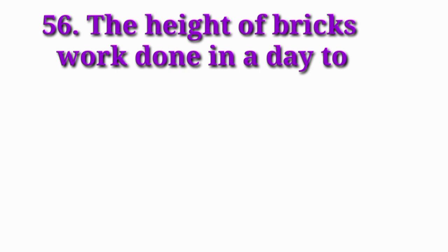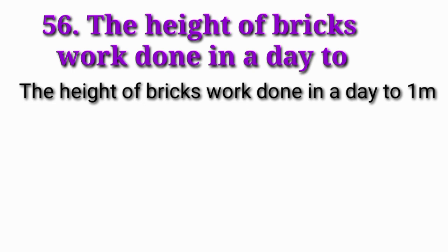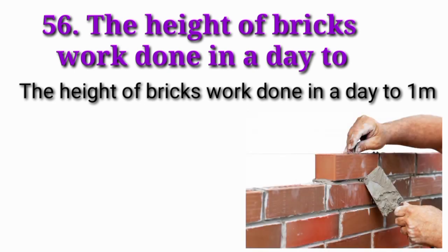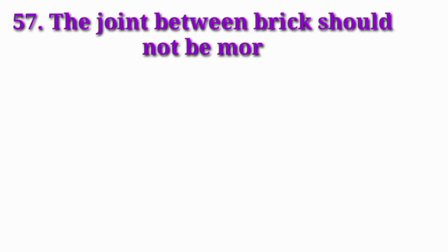Number 56, the height of brickwork done in a day. The height of brickwork done in a day is 1 meter. For a 5 inch wall, only 1 meter can be done in 1 day. For a 10 inch wall, something like 1.5 meters to 2 meters can be done in 1 day.